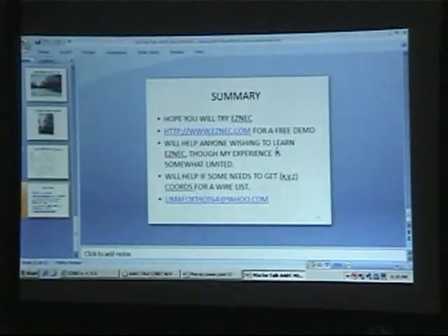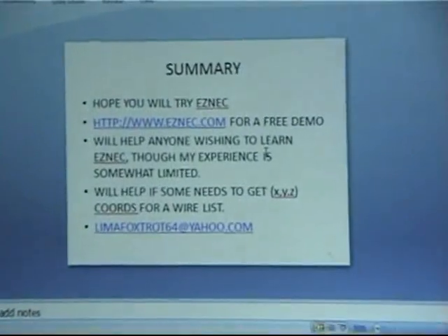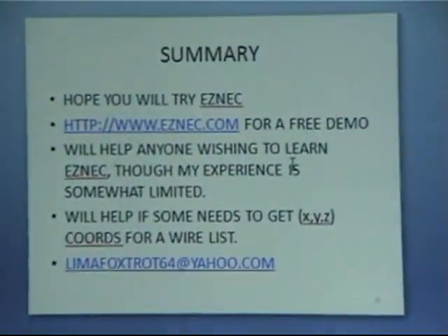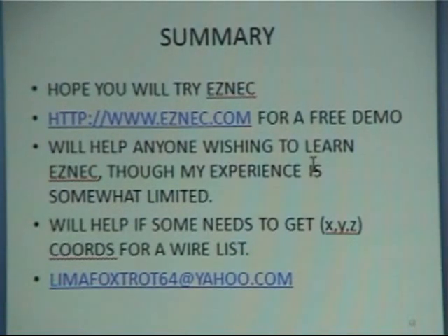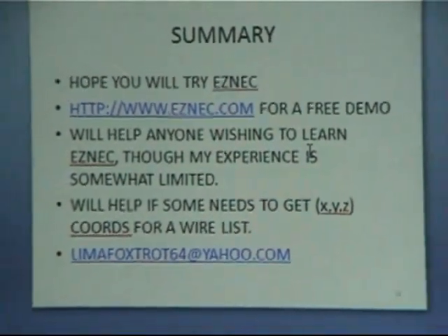So I guess the bottom line is some of the things that you can do with this. I've got a number of antennas that have some sort of arbitrary length dipoles. I feed them with 450 ohm line. One of the nice things here is you can run a model on that antenna at different frequencies, not just the half wave. It might be some unusual length, and you can run it and see what that pattern is.